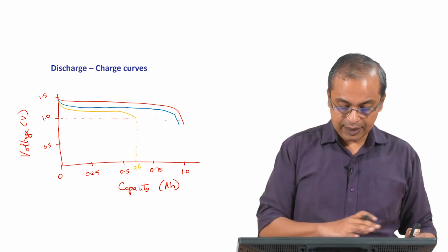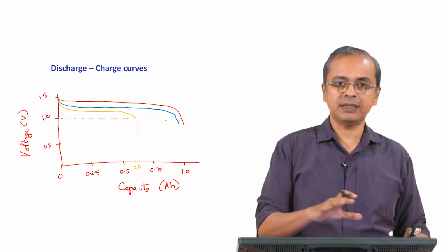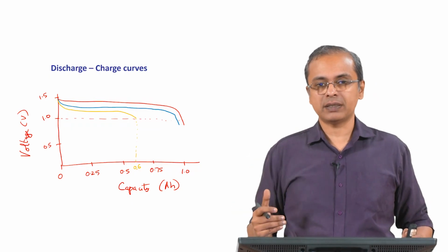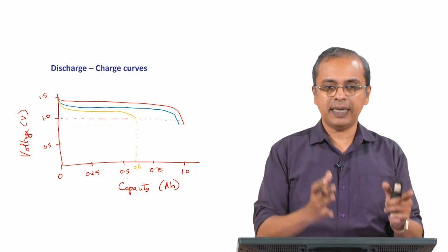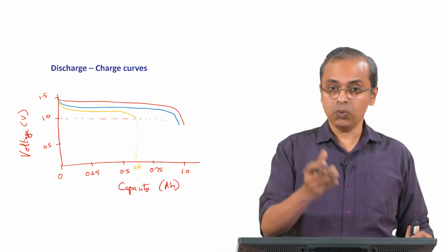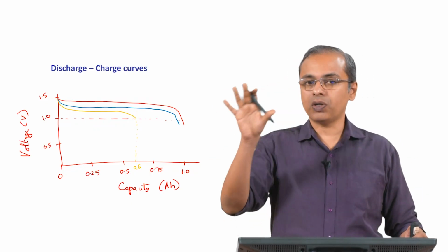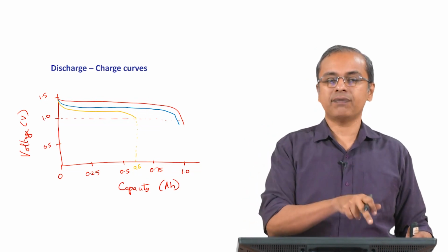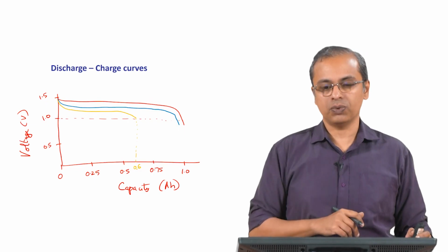So, the point is you have to understand that for different C rates the performance can be different. You may not completely get the full capacity out of it, and you need to understand this for your battery, so that you can tell clearly whether or not this battery can be put to use for some purpose. Or if you get a new battery that you want to use for some experiment or end use, you know how much current that use will draw, so you can test and check whether your battery can actually handle that activity, right. So, this is the way you would do that test.